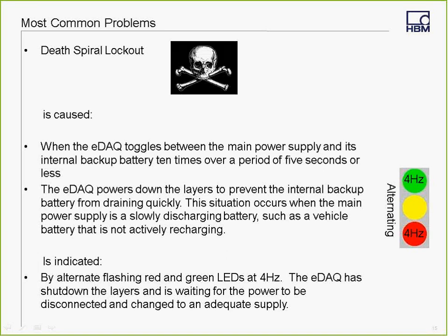This function was put into place to prevent a syndrome referred to as Monday morning eDAQ. We would often receive calls in regards to this. Normally they would occur after a weekend. An eDAQ would be left on, powered by a vehicle battery. It would slowly drain the battery down until it started oscillating on and off.